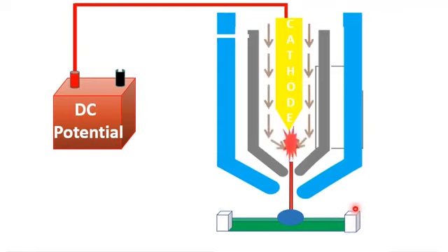Basically, in passive arrangement, a passive material like boron nitride rings is used at the edges of the cathode. Dear student, please note that boron nitride will confine the cathode spot onto the surface of the cathode. It will never allow the cathode spot to get out of the surface of the cathode.